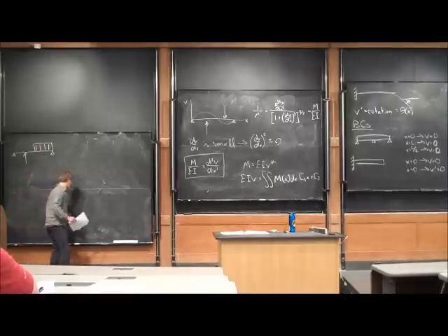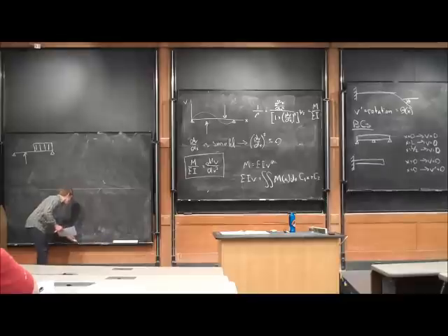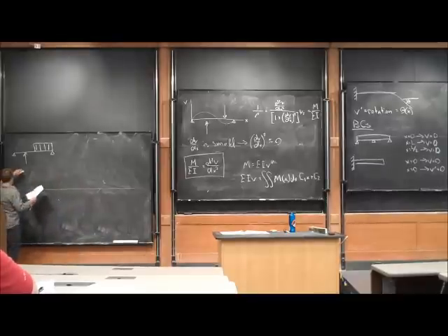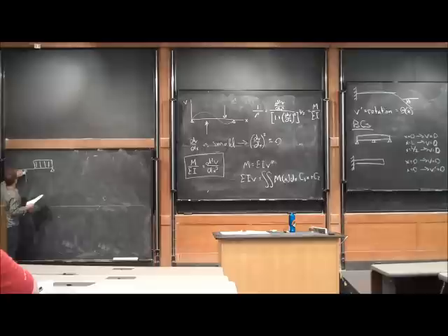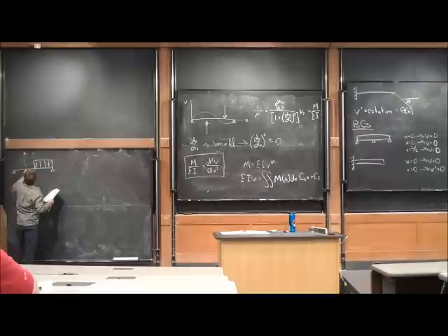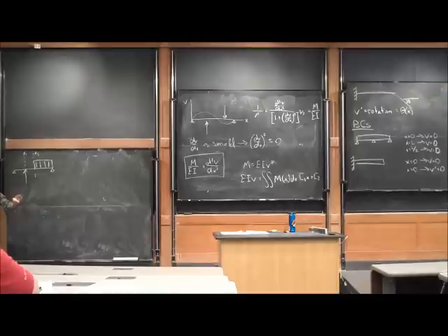So our last boundary condition is that if we have a beam with a complex loading system like that, where we have two sections, if I call this x1 and this x2, our deflection needs to be continuous across that transition.